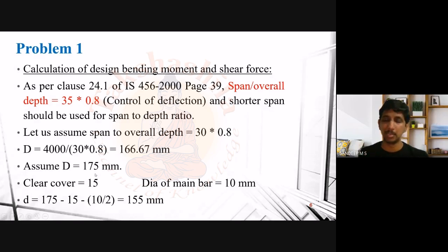And one more thing you have to understand is that for one-way slab, I have told you that in the normal case, we will be going up to a maximum depth of 15 centimeters or 150 millimeters. But in the case of two-way slab, that can reach up to 20 centimeters. Okay. So here, normally, since we have bending in both the directions, a little bit more thickness will be required for the slab. That is the reason.